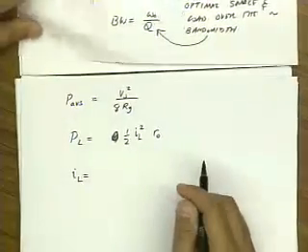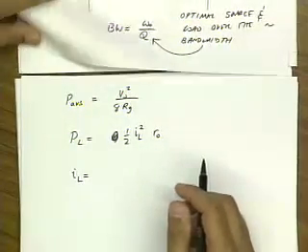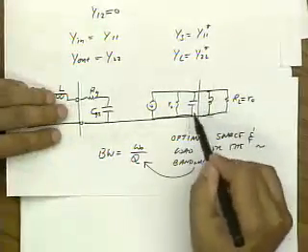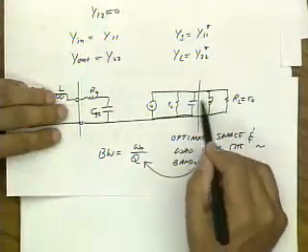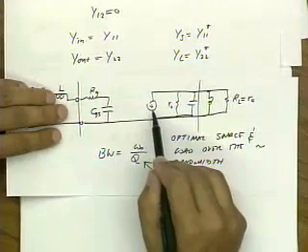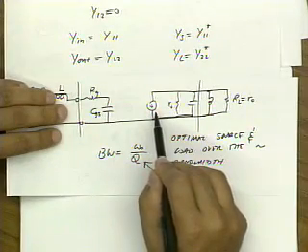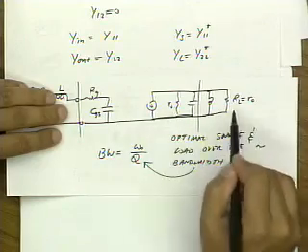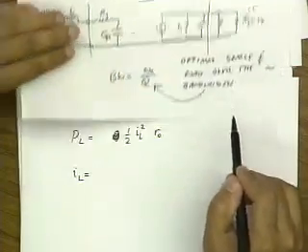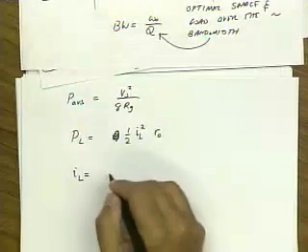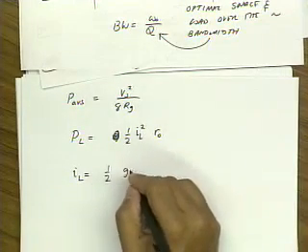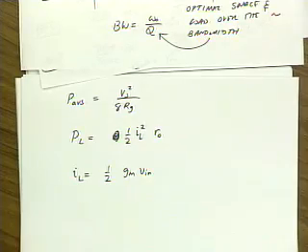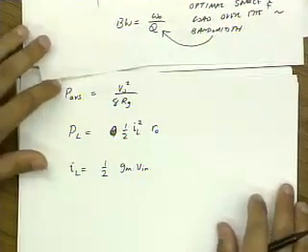Well, in resonance, there's a circulating current flowing between the L and the C, and so this current by this Gm generator all flows into the real resistances at resonance. So half of it flows here, half of it flows here. So we can say that the output current is 1/2 Gm times V in. Okay? So now we need to find V in.